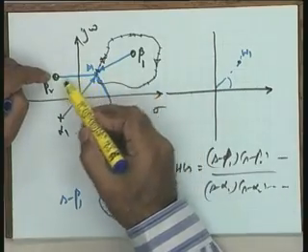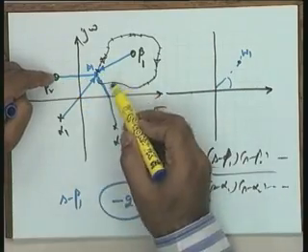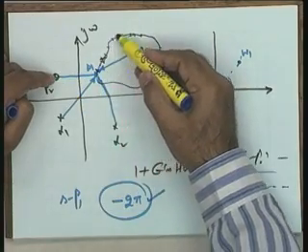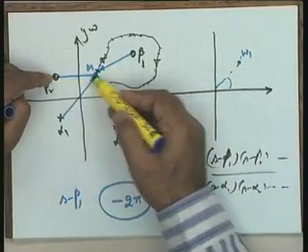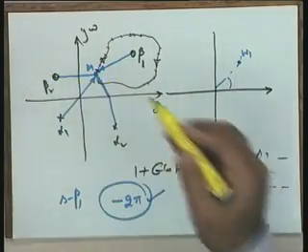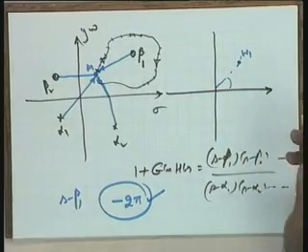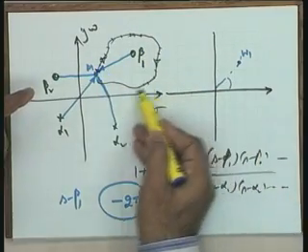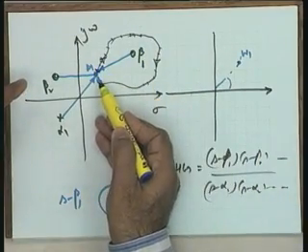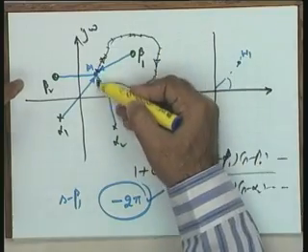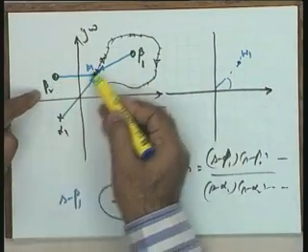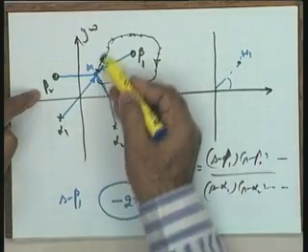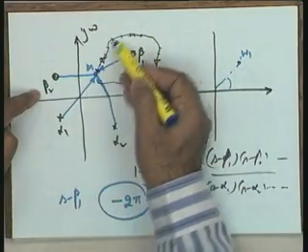Now look at the S minus beta 2 phasor. Start from here, go back to this and come back to this. The total angle contributed by the S minus beta 2 phasor is 0, because if this side is positive, there is a corresponding negative angle.